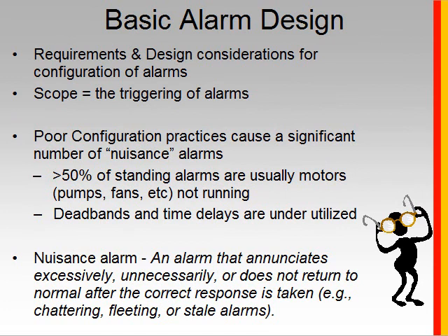Basic alarm design is actually one of the stages that affects the creation of nuisance alarms most heavily. So if you walk in a plant and you see that there's a lot of alarms that the operators are complaining about, or there's alarms that are displayed on the console all the time, chances are these are nuisance alarms, and most of the time they're there because poor basic alarm design has been used.